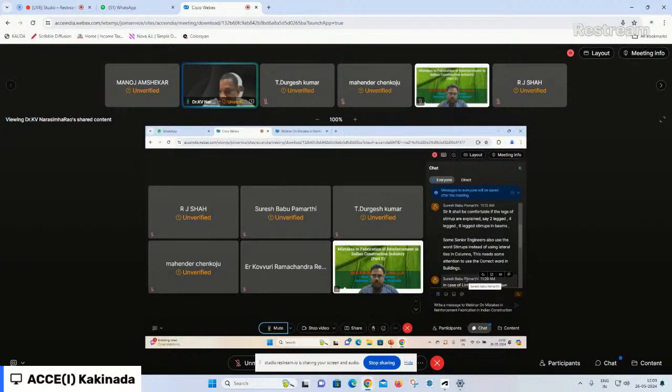Why? Because you already assumed in the design stage and the analysis stage that it is a release of the plate edge movements at the vertical face of the column. Bottom condition, there is no choice. That is the case of a fixed support condition. At the sides, there is a choice you have. Suppose during the design and analysis stage you have assumed that there is a release of the plate movements, that is, the stem of the plate movements. Then in that case, if the assumption in the analysis and design stage is release of the movements, you have to anchor the bar up to Ld/3 only, not more than that. If you have considered fixed conditions at the sides of the plate, then you have to anchor up to